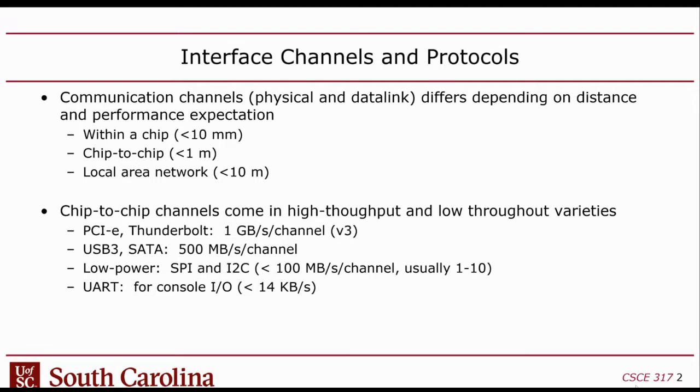All the work I did in grad school was based on chip-to-chip channels. We did optoelectronic channels. We did packaging where we bonded gallium arsenide chips, which allow you to do optical communication, to CMOS chips using, as I mentioned, silicon on sapphire, and then we connected them to fiber image guides to build these packages. We also did multi-bit differential signaling. Basically, it was all chip-to-chip link stuff.